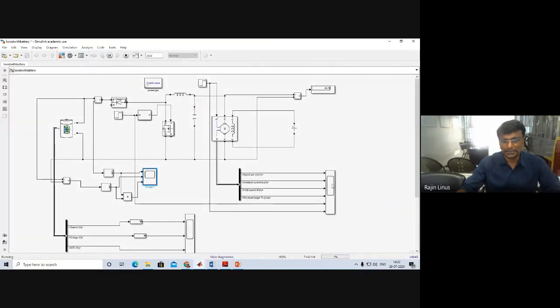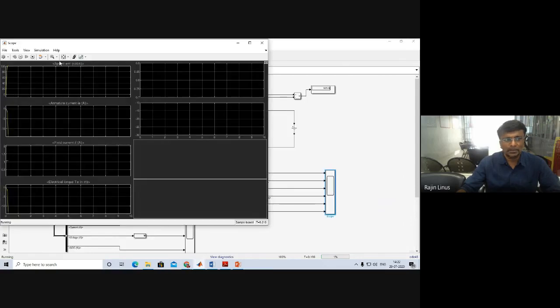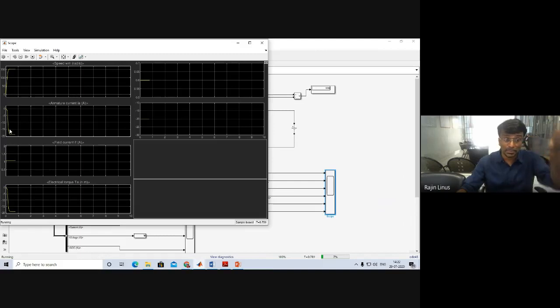So in these 10 seconds, what happened? As the speed is increasing, the armature current is negative. The reason is direct: previously, with the buck converter, the armature current was positive, here the current is fed back, that is why it is negative, but the field current is the same. Then the electromagnetic torque is also negative, because it reflects the armature current.